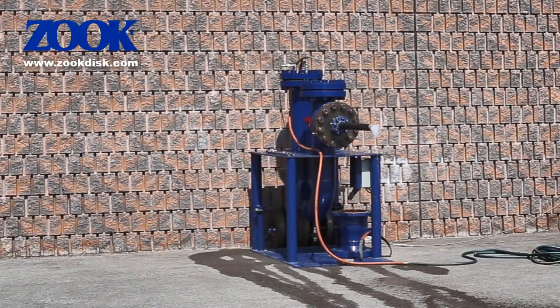So you can see from the video, a compressed gas has far more stored energy than liquid, and the burst event is much more violent. In terms of rupture disk design, a gas burst poses significantly more challenges to the rupture disk engineers. A simple way to explain what a rupture disk is: it is an engineered weak spot in a pressurized system that ruptures at a designated pressure. Very similar to what a fuse does in an electrical system to prevent an unsafe condition.